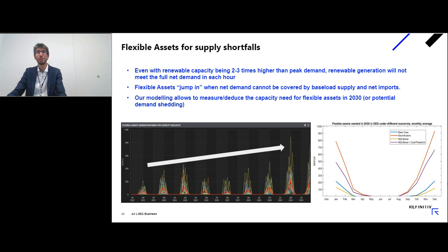So you can see in monthly resolution, it doesn't look too high. In 2030, in Germany, for example, we see an average monthly across weather scenarios of 200 megawatts. We say, okay, that's nothing. But now I will tell you a lot more about this story, because already you can see that across weather years, this 200 megawatts, which is this base case here, for a month of January, will have a variability in terms of average monthly from close to zero to close to 1 gigawatt. But now in the next slide, we will see what this means in hourly resolution.